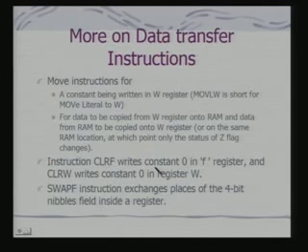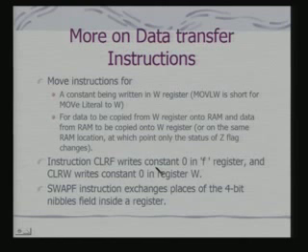So now if we can summarize what we have seen in particular for byte oriented data transfer operations, we have provision for writing onto the W register through immediate mode. That is, the literals can be copied to the W register.